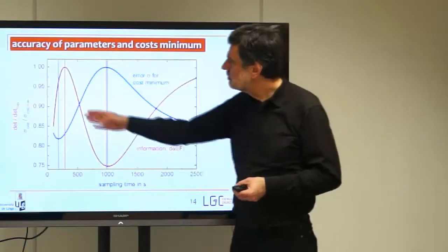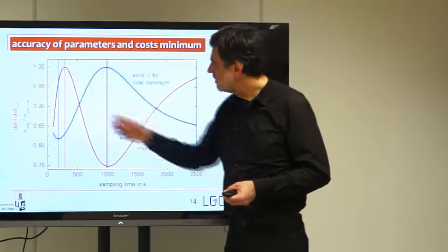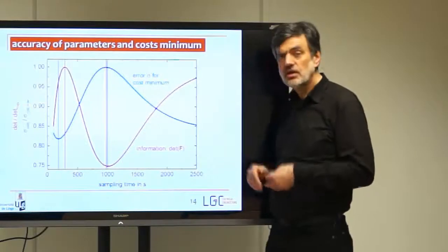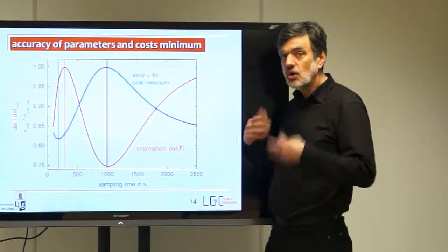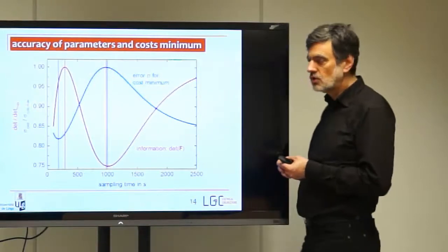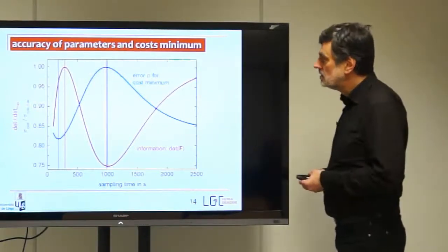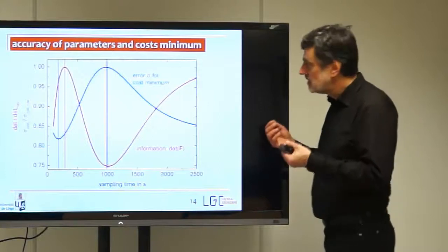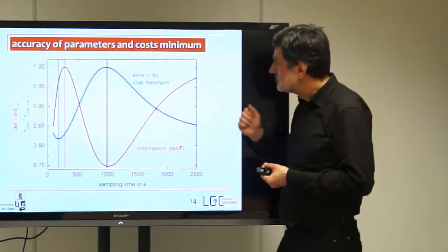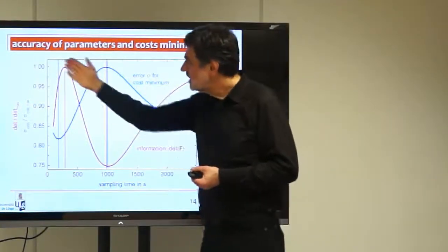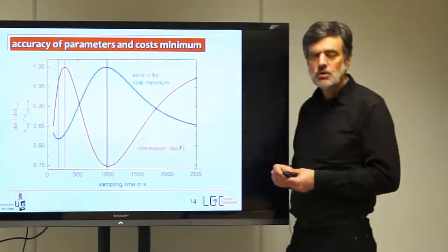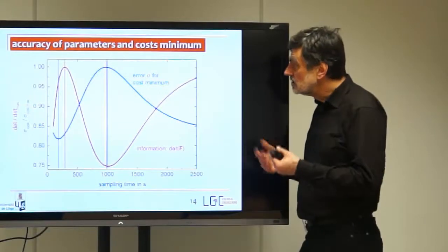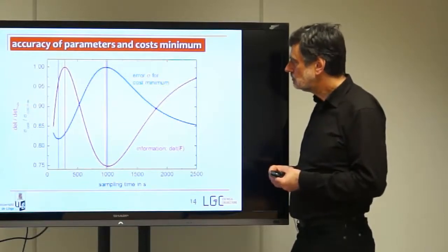And you see that the information is, as I said, somewhere high up here and somewhere high up here. I discussed that. This is more or less a diffusion coefficient. This is the overall concentration of the transfer component in the solid that is characterized by this maxima. So here you get the concentration accurate. Here you get your diffusion coefficient accurate. In between, you don't get too much information of either of these values.